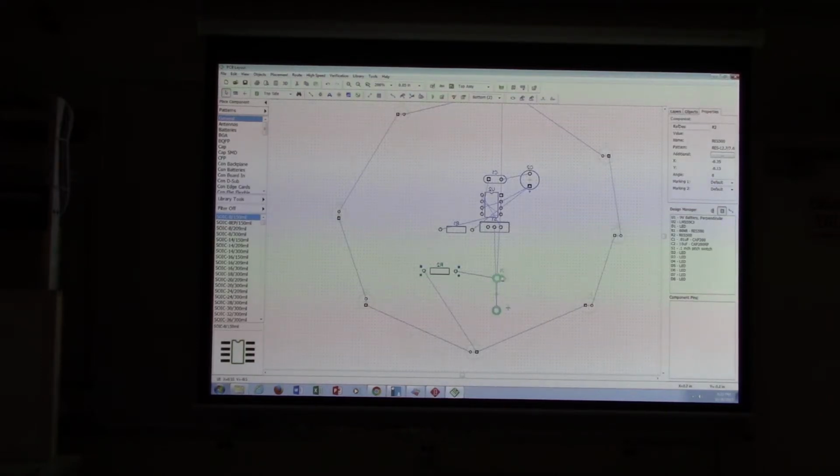My thought was that you could use this battery as sort of a stand, so you could lean the part on this battery. That's something to keep in mind when you're doing your design. Again, you just do your best to get the components laid out in such a way that there's not too many rat lines crossing, and then you call it good.